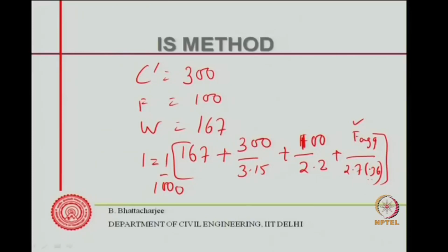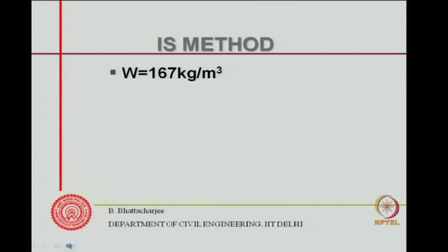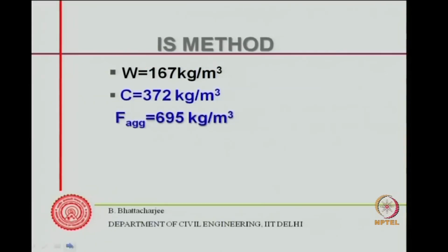So, 300 if you use fly ash alone, 280 if you use a superplasticizer, but it would be much less, let us say 25% less than the amount that you are using. So, 126 liters with the fly ash, the water cement ratio is such that you can actually reduce down still more the cement content. Right now one can understand from whatever our discussion has been. So, this is how, up to this, we determine the mix design, mix proportions, and let us see how we do the